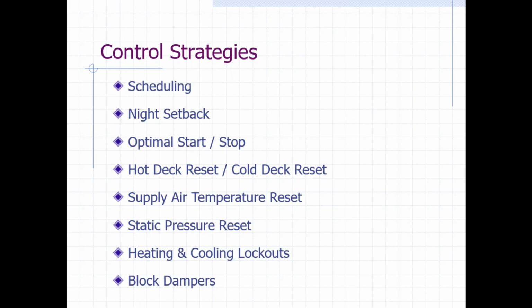And it does the same for starting. If everybody shows up at 6 in the morning, when should we start it? Should we start at 4, 5, 5:30? It will look at the outside air temperature, the zone temperatures, and its past experience trying this, and it will decide when to start the air handlers. So that's optimal start stop.